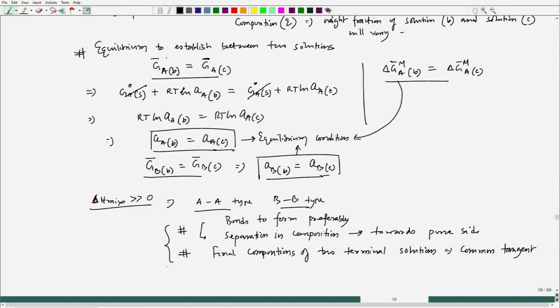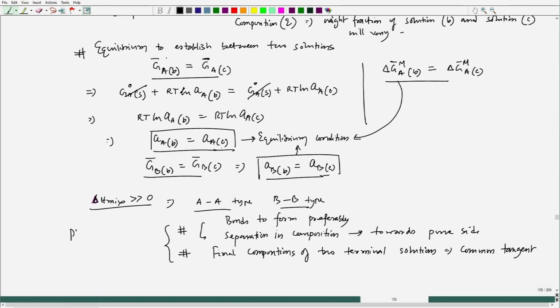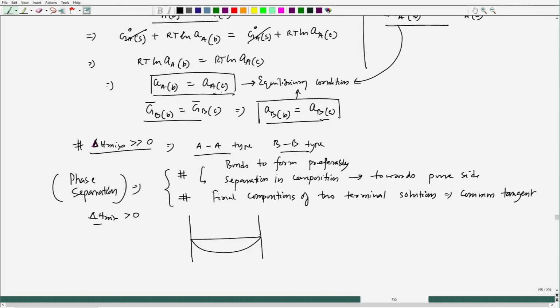and this entire thing is basically one single phase breaking into two phases of two different compositions, and those are actually solutions. So, that is called phase separation. Fine. So, this phase separation is arising because of this particular condition, but if this is small negative, small positive, in that case the delta G mix plot becomes like this.